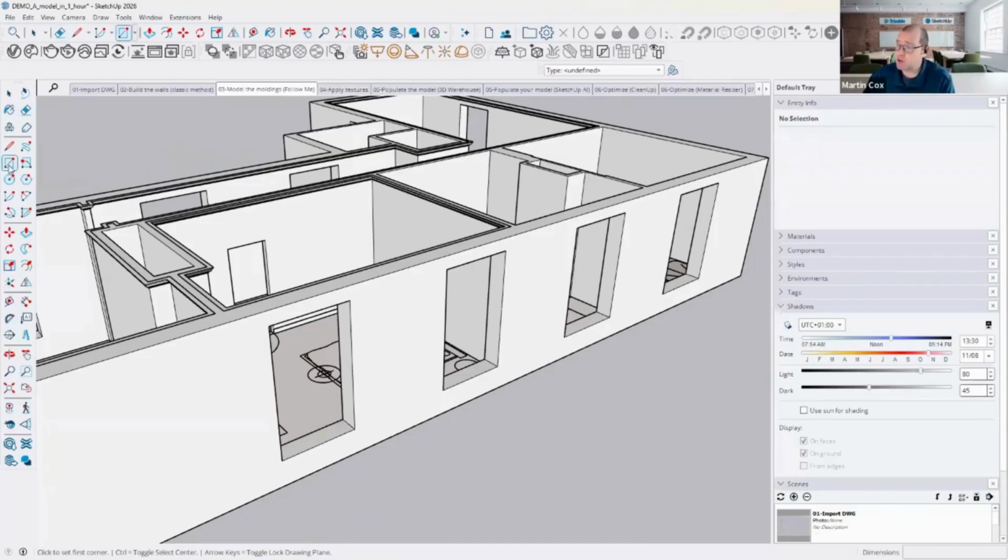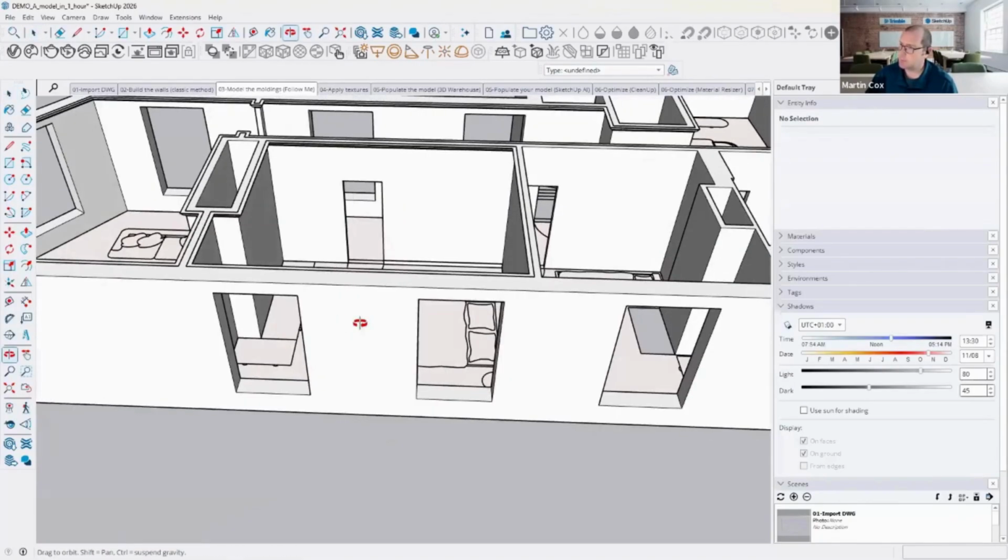The other option is when you draw a rectangle, if you look down at the bottom right-hand side of my screen, it's giving me the dimensions of the rectangle, and I could actually just type in, if I want to show a rectangle that we can see here, 2 meters, 1 meter, that will draw a rectangle that size for me. So the accuracy that you can have in SketchUp, you can literally go down to like 5 points in a millimeter. So the accuracy is quite high there. Okay.